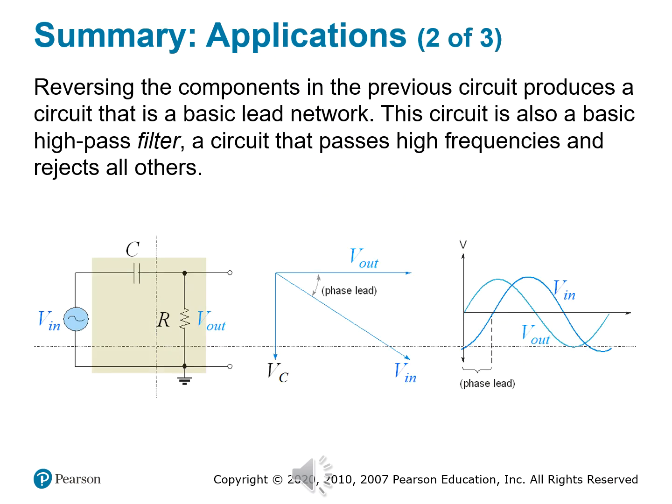RC applications, part 2. So last time we looked at how a series RC circuit acted as a phase lag generator and a low pass filter. But what happens when we reverse the resistor and capacitor? We've done this before with the RL circuits, right? We enter the world of lead networks and high pass filters. So just reversing components reverses the behavior, and it's just where we're taking the output from. Remember, these things are happening simultaneously within the circuit.